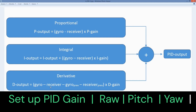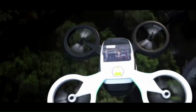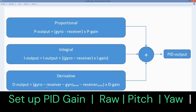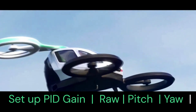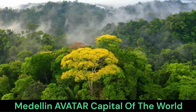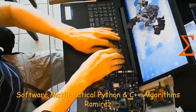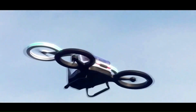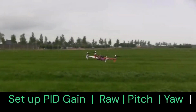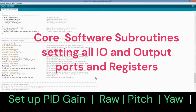That is the gain settings for roll P controller, gain settings for roll I controller, and gain settings for roll D controller, and also the maximum output of the PID controller. Now let's set the gain for the pitch PID, and set the gain for the yaw PID controller.